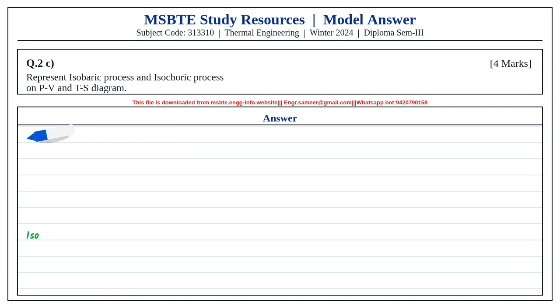For steam turbine, heat loss, potential energy change and kinetic energy change are usually neglected. Therefore, turbine work is H1 minus H2. For steam boiler, no shaft work is done and changes in kinetic and potential energy are neglected. Therefore, heat supplied is H2 minus H1 and for mass flow rate m, Q is equal to m into (H2 minus H1).